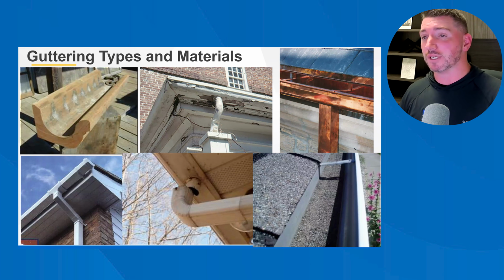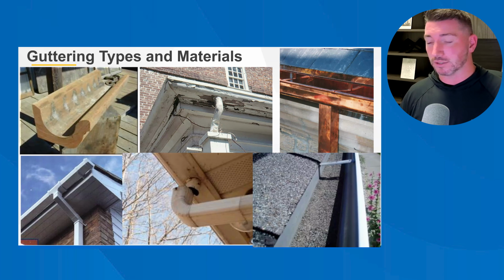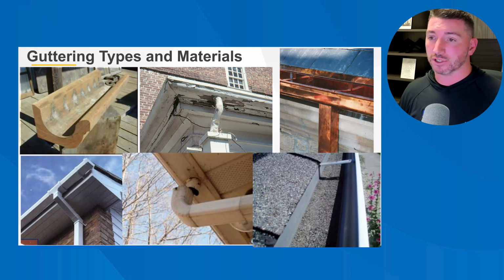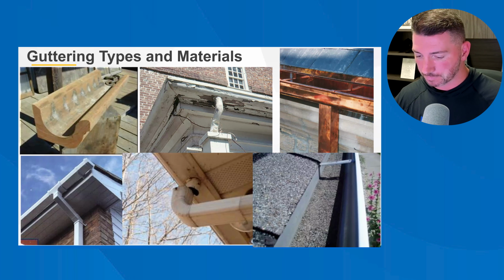And then if there was a recent hailstorm, even sub-severe hail that's very small can dislodge granules from the roof. Not any more than rain or walking on the roof would dislodge some granules. So it's not necessarily damage, but in an instance of a heavy rain or a hailstorm, you can have excess granules found in that gutter.